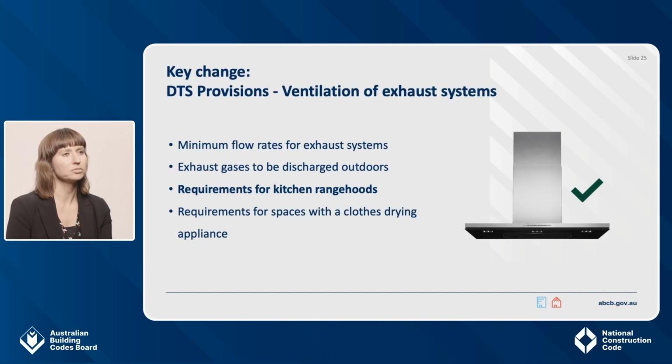Similarly, for a bathroom, sanitary compartment or a laundry, NCC 2019 required these to be ducted directly to outdoor air or to a ventilated roof space. NCC 2022 requires all these to be ducted directly to outdoor air. You can no longer have exhaust gases ducted to a ventilated roof space.